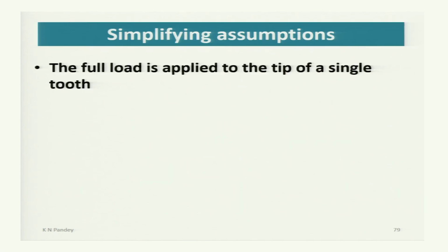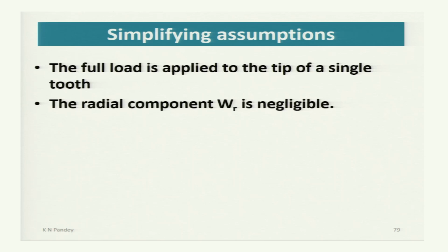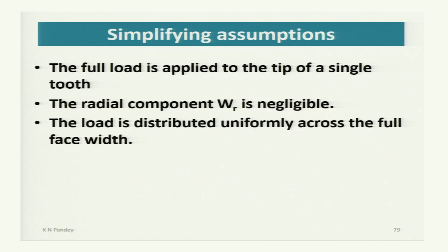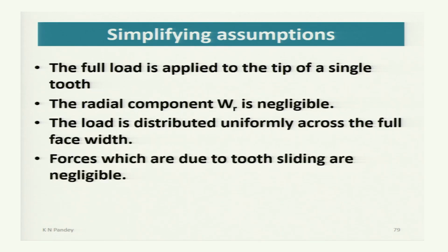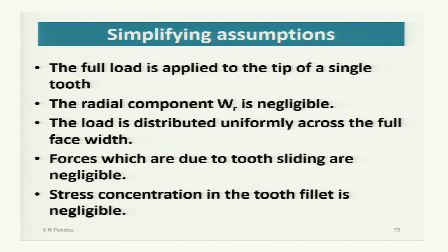Now we applied some simplifying assumptions. The simplifying assumptions were: the full load is applied to the tip of a single tooth, the radial component Wr is negligible, the load is distributed uniformly across the full face width, forces due to tooth sliding are negligible, and stress concentration in the tooth fillet is negligible.